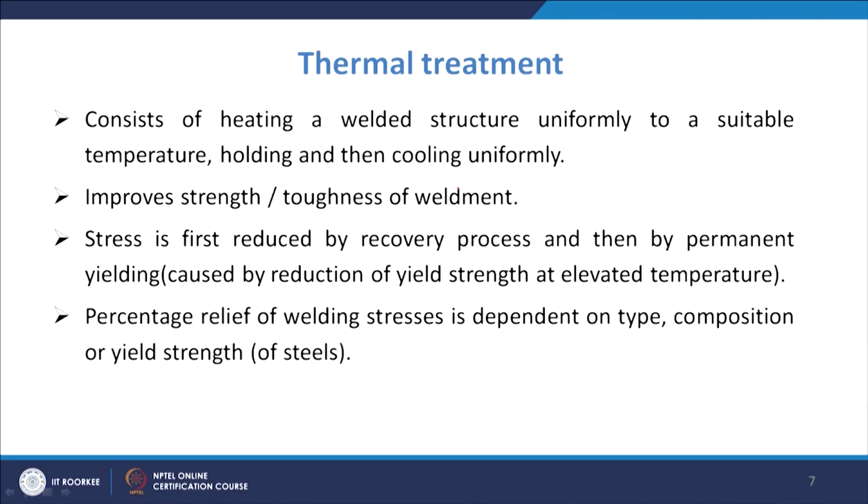What happens in this case is that the stress will first be reduced by the recovery process, and then by permanent yielding. That is caused by the reduction of yield strength at elevated temperature. Because you are increasing the temperature, you will have a reduction in the yield strength. Because of the recovery process the stress will be reduced, and you have permanent yielding also taking place.